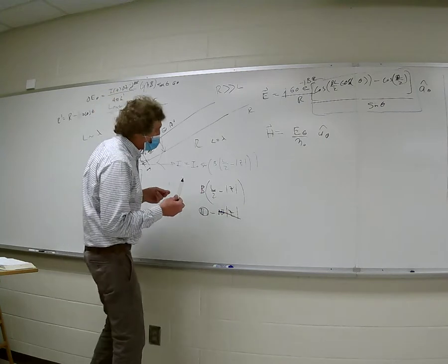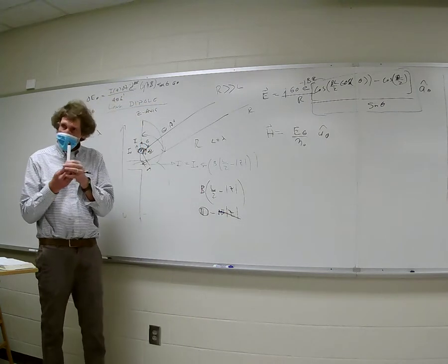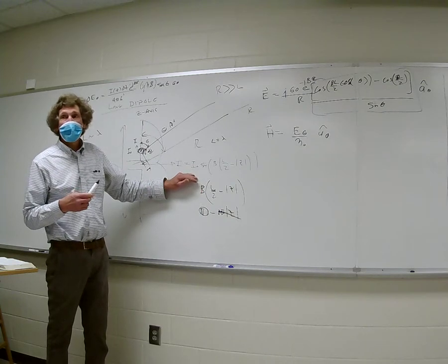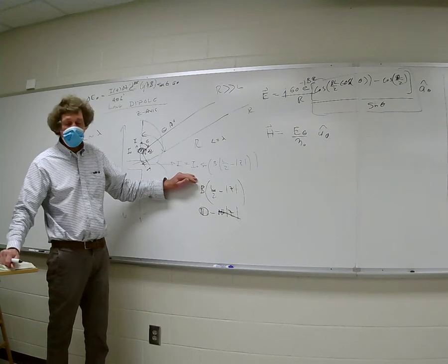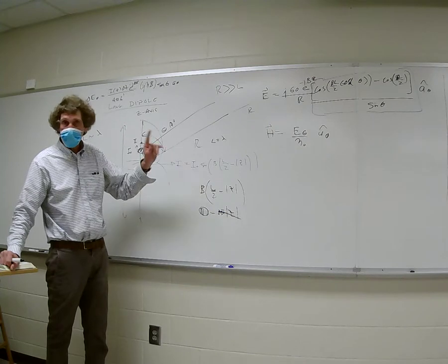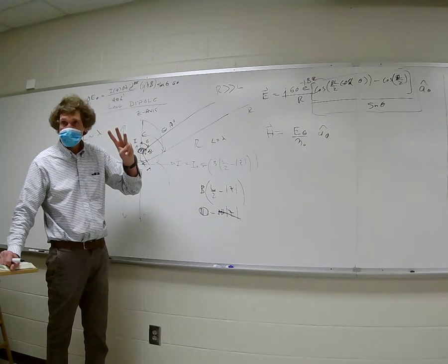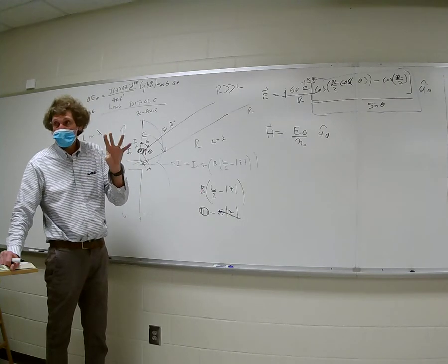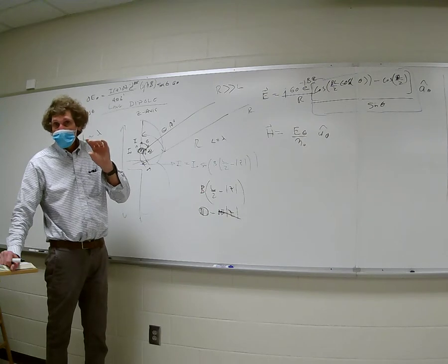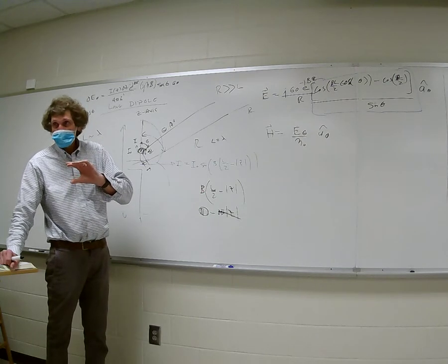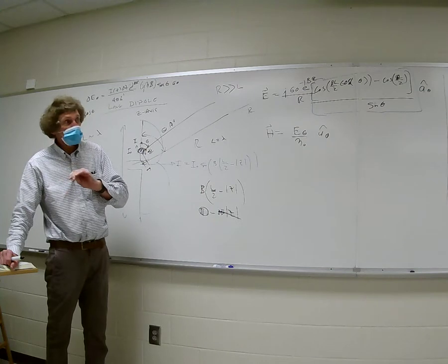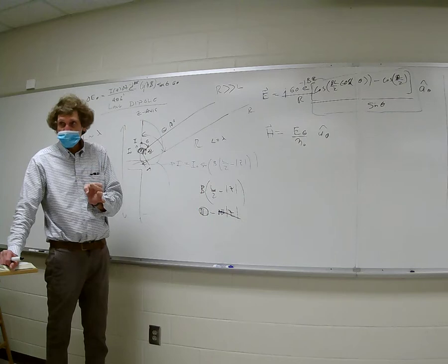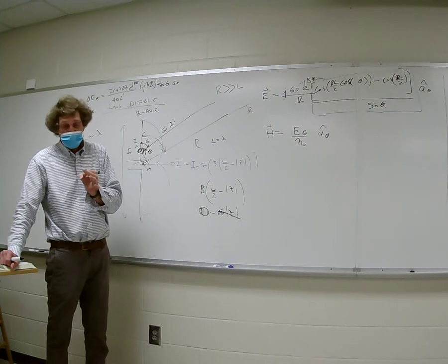There are other things. But in general, in Wentworth's book, he's assuming they're very thin and that this is a good approximation of the current. It is. The antenna will have a maximum impedance when it's any even number of wavelengths long: 1 wavelength long, 2 wavelengths, 3 wavelengths, and such. You'll get a huge impedance, which is tough, means you can't couple much power. You follow me on that? All right. Now, there's more to this, and I don't want to spend a lot of time on this, but remember that the wire's radius plays a role in the actual driving point impedance, and whether it's a full wavelength or whatever it is.